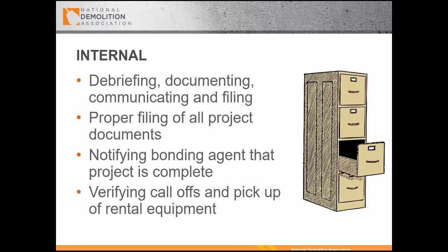Proper filing of project documents, most of it's electronic these days, but you should have a system that you should be able to find stuff in less than 5 minutes. If it's taking you 10, 15 minutes to find something, you need to rework your filing system, whether it's electronic or hard copy. Notifying your bonding agent that the project's complete is very wise. That will free up bonding for other projects. And verify everything's been called off and picked up on the rental equipment, oxygen bottles, propane, those types of things, temporary fence.